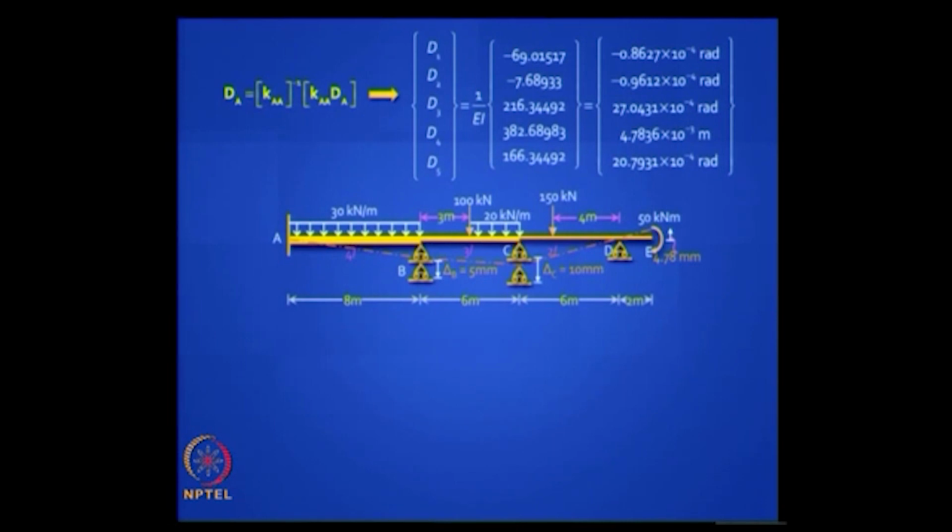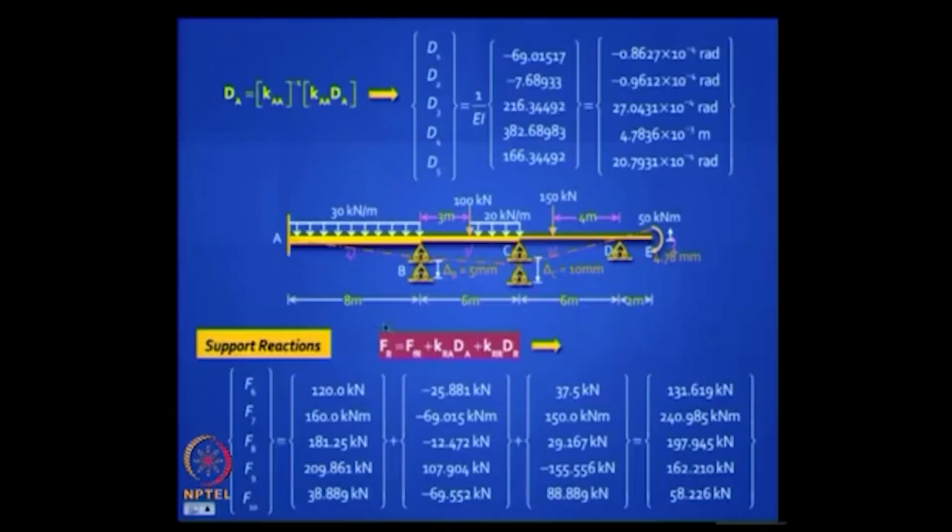Okay, now what is the next step? You have got the active displacement. Next step, support reactions. Take the second equilibrium equation. This is where your fixed end force vector comes in. Remember FFR, which you calculated and stored, and you have KRA dA and you have KRR dr, multiply them out, you have these n moments. Yes, any doubt?